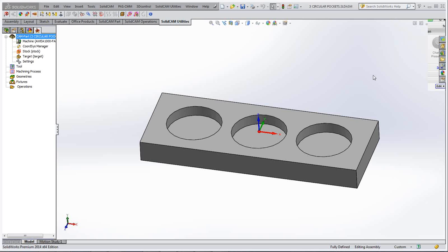set of strategies to use, and I would encourage anybody who's got 2.5D milling to familiarise yourself fully with the toolbox cycles, because there's lots of things in there that are pretty much like shortcuts. If you're not doing something that's really complex, before you go to a profiling strategy or a pocketing strategy, have a quick look at what's in the profiles in the cycles to help you out a little bit. I'll be dealing with 2 or 3 of the new ones that have been added in there. Okay, first thing I'm going to look at, seeing as I've got it open already, this particular model.